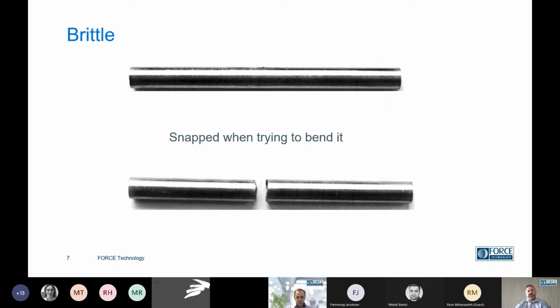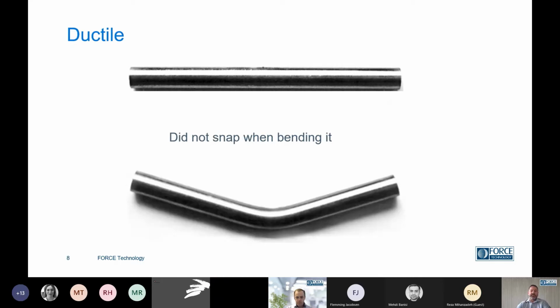Okay, so in case there's some of you who are very new to this, I'll start very basic and I'll ramp up a little bit. So let's introduce the word brittle. And what does it mean? Very basically, you take something and you bend it, or you're trying to bend it, and if it snaps, it's brittle. Important thing is there was no deformation.